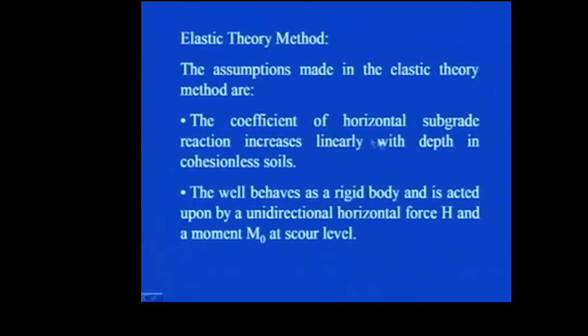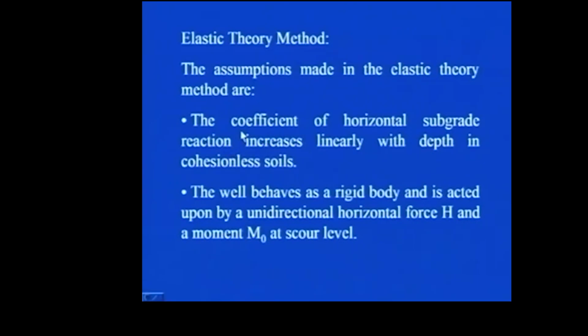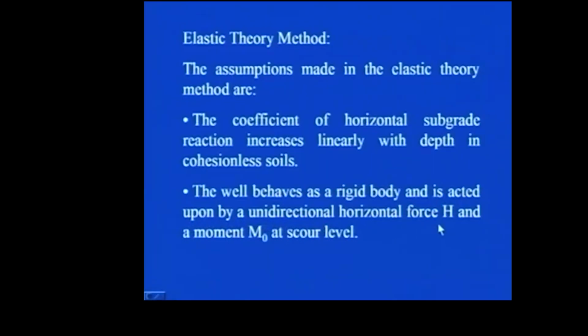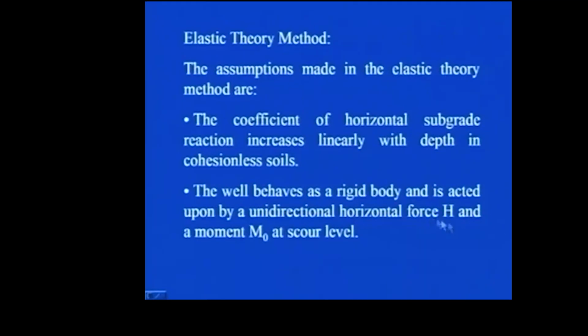The coefficient of horizontal subgrade reaction increases linearly with depth in cohesionless soil. Okay. So, this is again another assumption. It may not be true in practical cases, but this is the assumption associated with the elastic theory given by IRC. The well behaves as a rigid body and is acted upon by a unidirectional horizontal force H and a moment M0 at scour level. So, this is again a horizontal force H acting only in one direction, and a moment is also present at scour level, which is represented by M0.